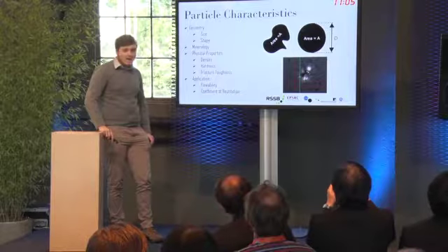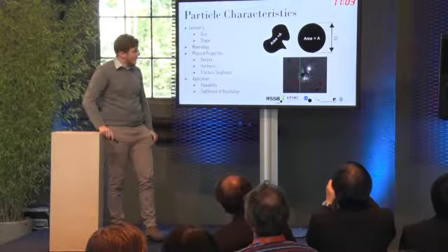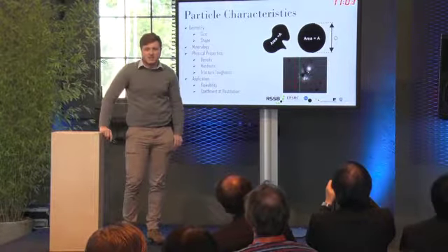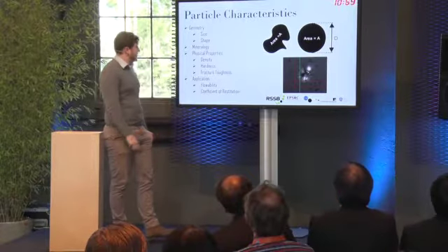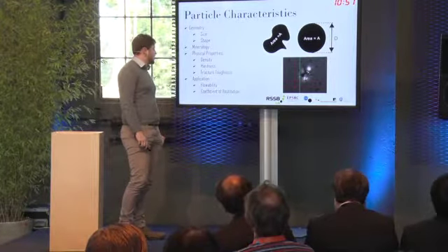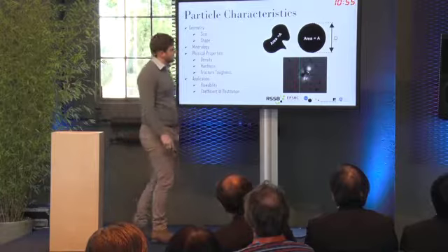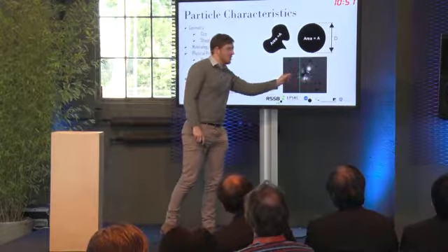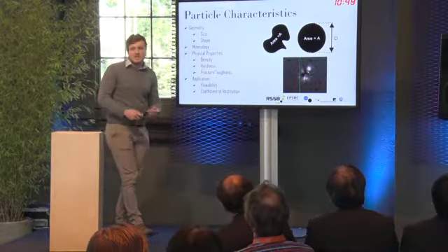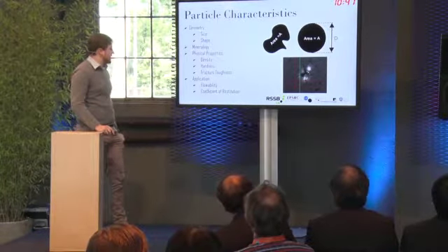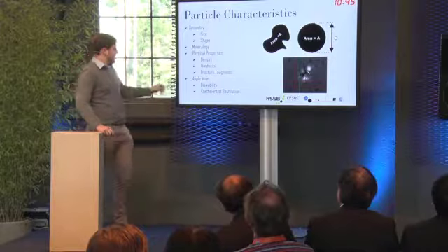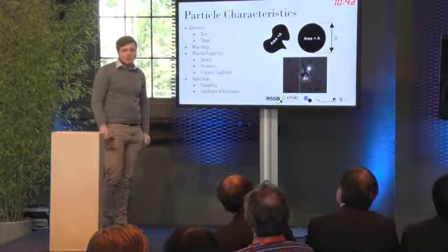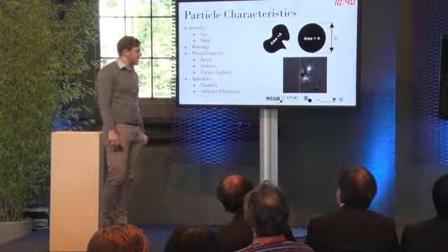I had a look at hardness using both nano and micro indentation. And from this micro indentation, I also looked at fracture toughness, so creating cracks in my specimen, then measuring off those cracks to get an idea of what sort of fracture toughness I have.